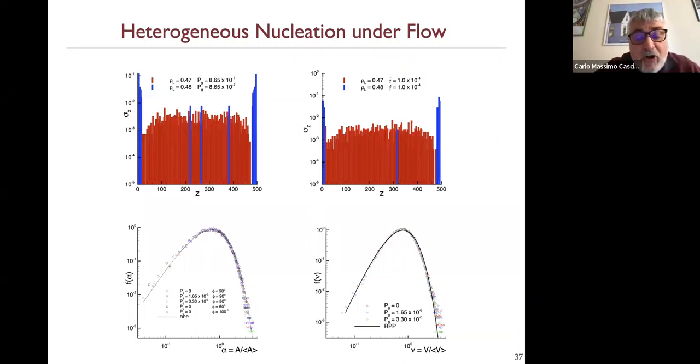So you see that the symbols more or less follow quite precisely the Poisson model prediction, but there are slight deviations at very large and very small areas. So this means that there is a certain tendency to clustering, meaning that there is a certain probability that where a bubble has already nucleated, there will be another bubble nucleating very close. The deviation is not extremely strong, but it's clearly visible in the result, in which the sizes of the symbols correspond to the statistical accuracy of the data.